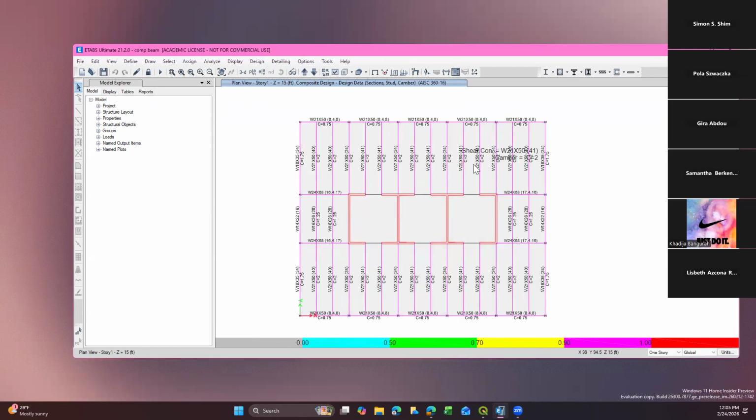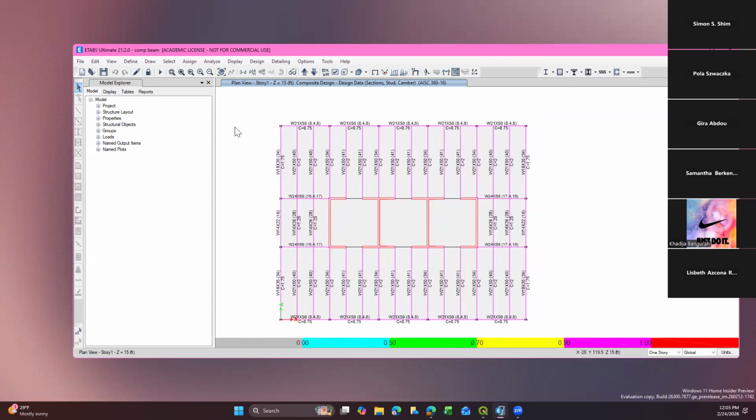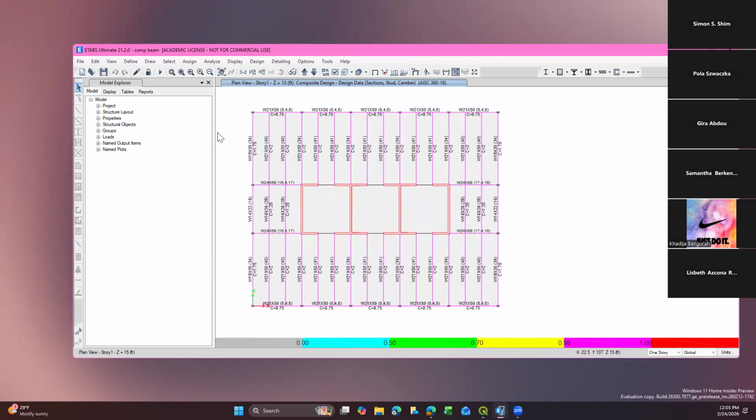Okay, what you see, the member size is updated. Now everybody think about how to present your design. Start with your building floor plan layout. Explain the typical geometry of your project. You have a typical building of 1, 2, 3, 4, 5 bays, 30 by 5 is 150 feet by 45, maybe 90 by 120 feet floor plate. We have a typical bay of 30 feet by 45.